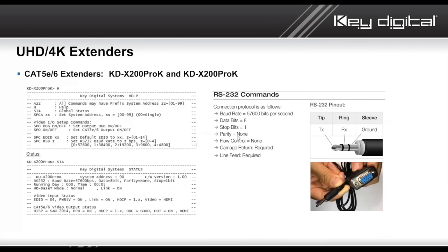You can turn on debug mode, a very valuable tool. This debug mode allows us to change where the HDCP is authenticated from our device to the display or vice versa. Why? Because HDCP is a fact of life. Displays now support HDCP. Your HDMI ports on your devices all support HDCP.